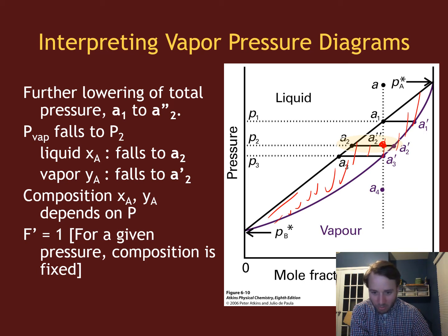So this equilibrium is no longer just a straight line, right? In a single component phase diagram, the equilibrium between the liquid and vapor phase is a line. In a two component phase diagram, that equilibrium is a surface, a plane. It's not just a straight line. So within this region here, I have both the liquid and vapor phase in equilibrium with each other.